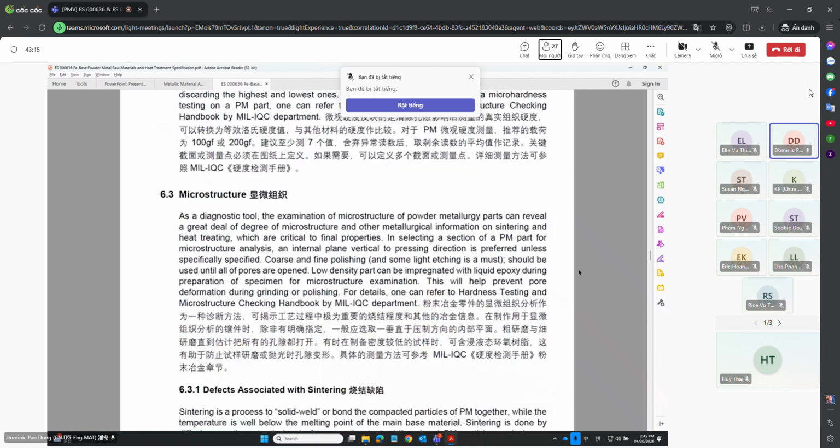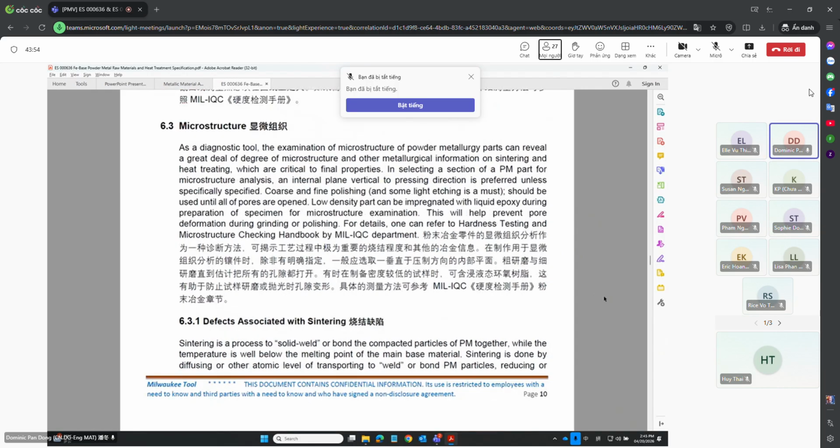And here the next section is about the microstructure. For microstructure sample building, of course, we need to do the cross-sectioning. So I hope you have already established the capability inside your lab to wire cut the parts, mount them, grind and polish them, then chemically etch them until you can get a very clear and sharp image of the microstructure, to tell you what kind of defects are there or how good your microstructure is.